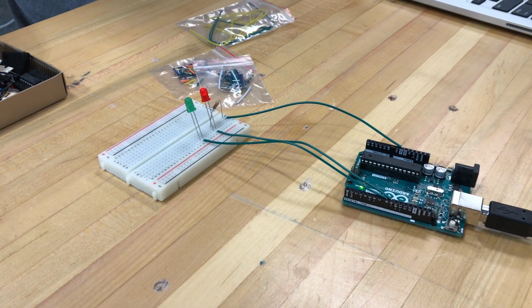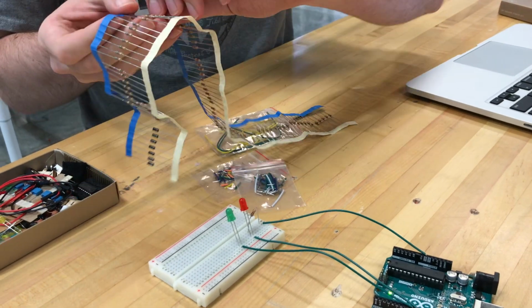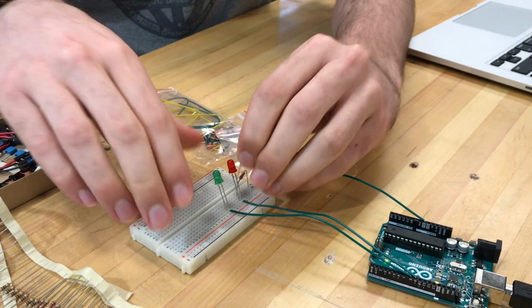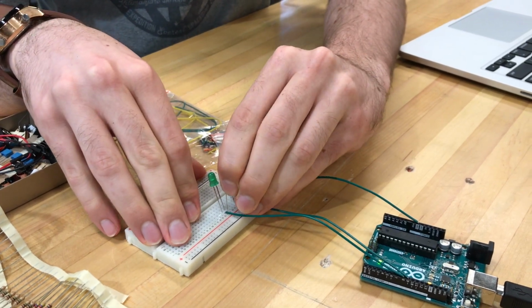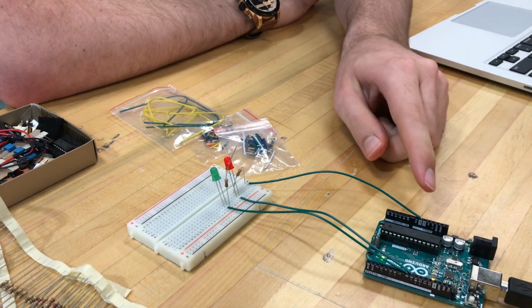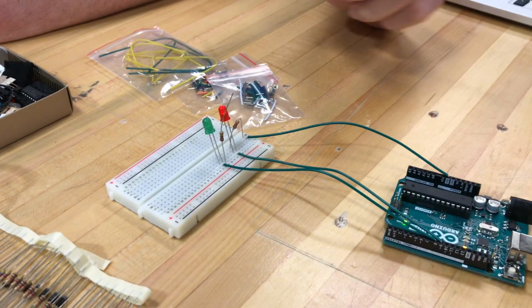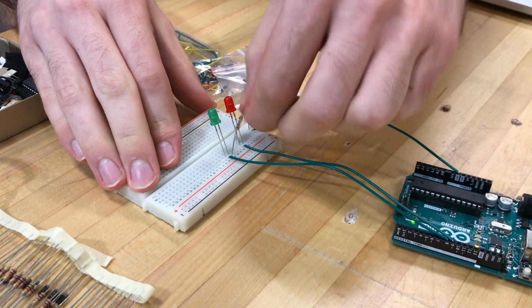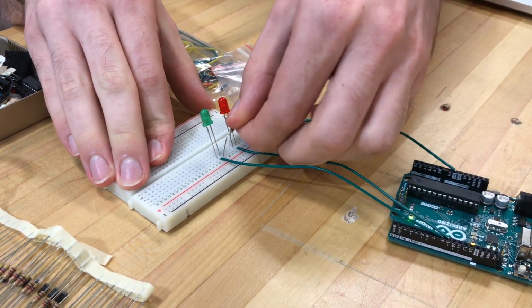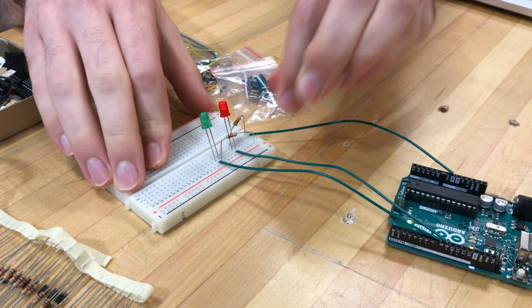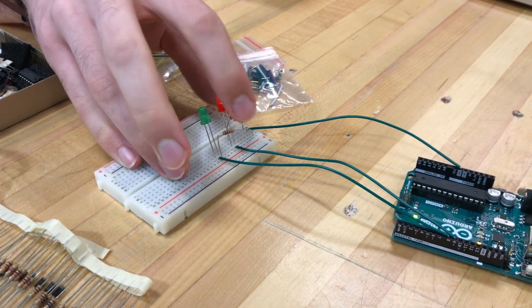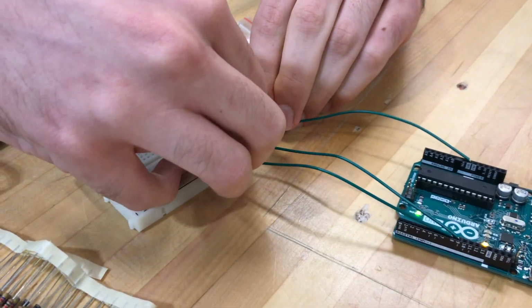The other end needs to be connected to another 1 kilo ohm resistor. And we already have a connection to the ground pin on our circuit board, so we don't need to run another wire to ground. We can instead share a wire between both circuits. Hence, I'll plug the other end of this resistor into the same line as the ground from the first LED circuit.